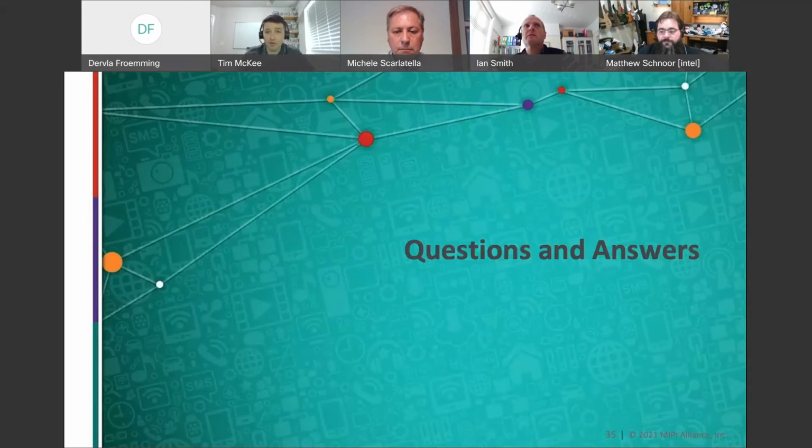So Matt, I don't know if you want to add anything. I know you've got some deep workings in with some of these liaison works. Yeah, I think the cases in development fall into two categories. Number one, how do we bridge I3C and provide access to remote use cases from further away networks? I think the IEEE 1722 and A-PHY are the two classic examples of that. And the other is, how do we take existing things and bring them into I3C, which is PCIe sideband, ETSI for Smart Secure Platform, and other use cases. So I think you see these fall into two general groups. I hope that explains what the questioner was asking.